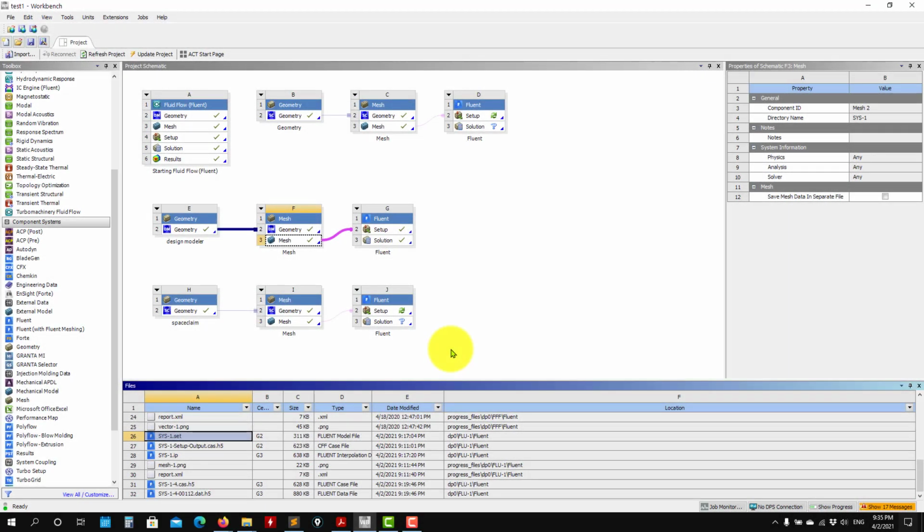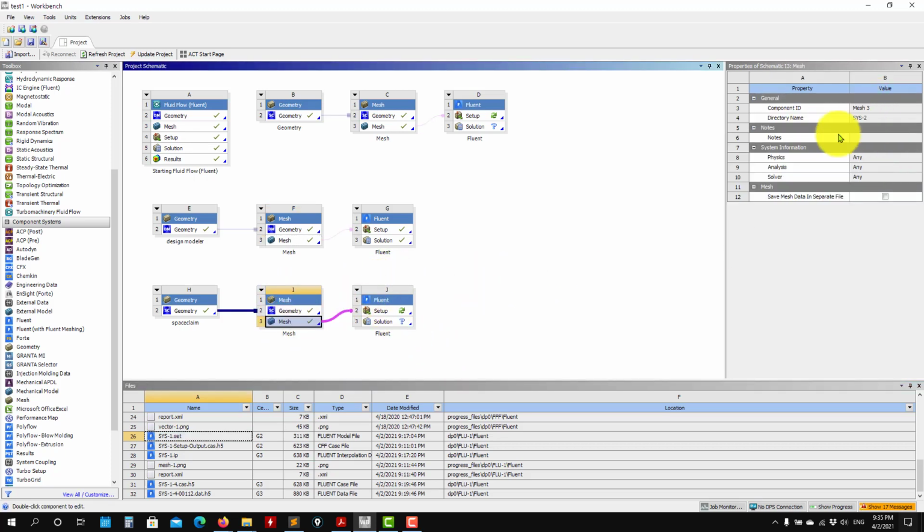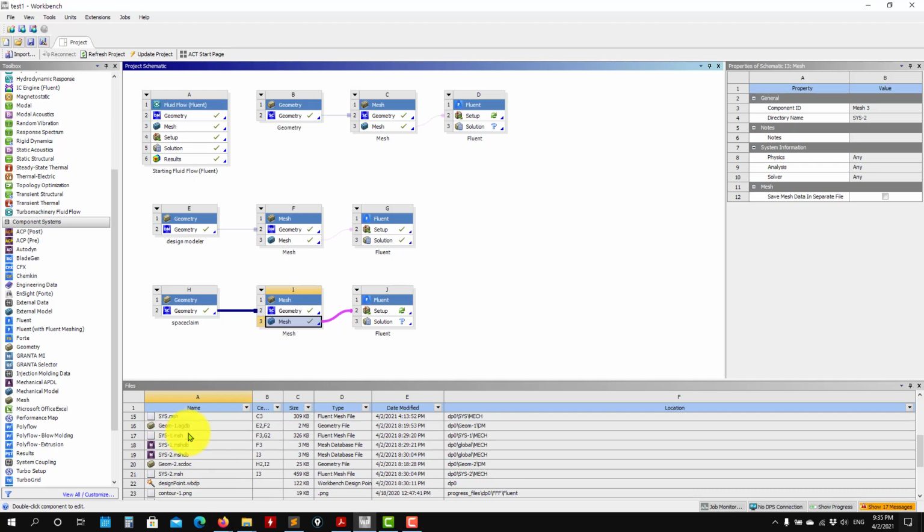Okay, welcome back. So now let's work in the same case, but now let's set up everything in Fluent standalone. At this point, you can close your Workbench, but remember that you can explore here now. You can know where the location of these files is, these two. So you just need to copy the mesh files that you have for the mesh.